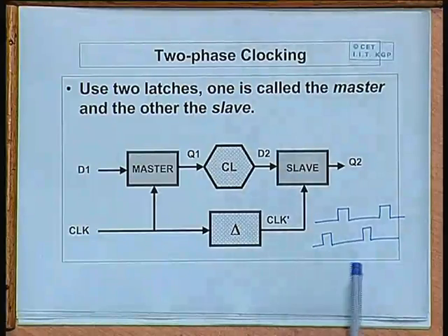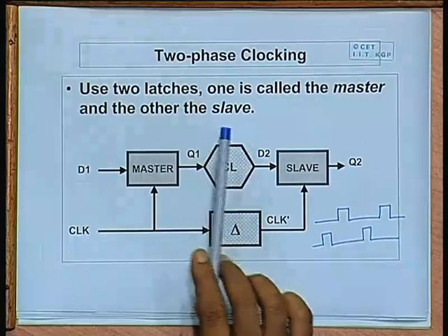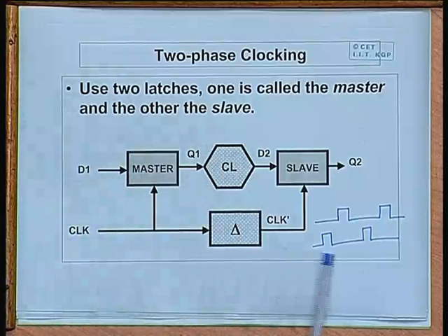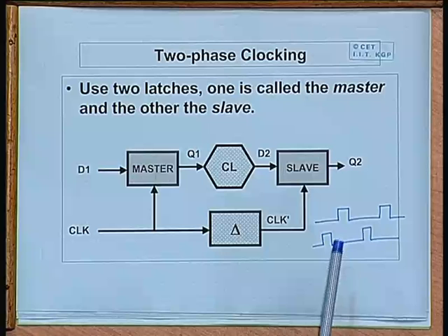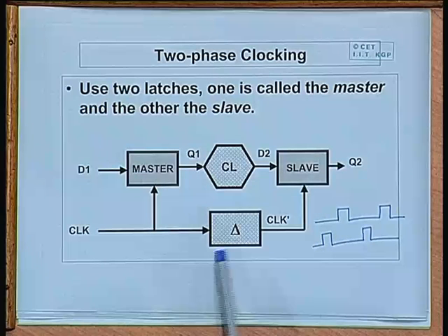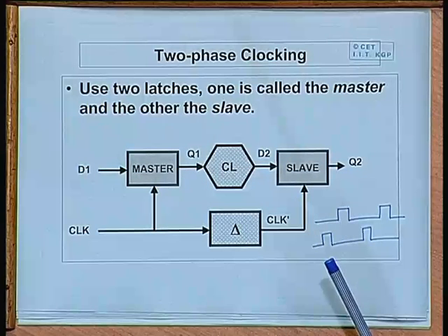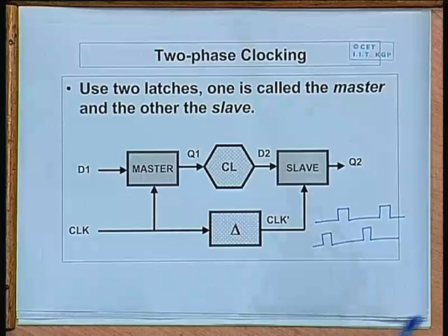Okay, so I am not going into details of this, all these things you know. So, irrespective of whether it is single phase or two phase clocking, the issue of clock skew remains equally important. So, if we can minimize clock skew, we can run this circuit at a higher speed. Okay, fine.